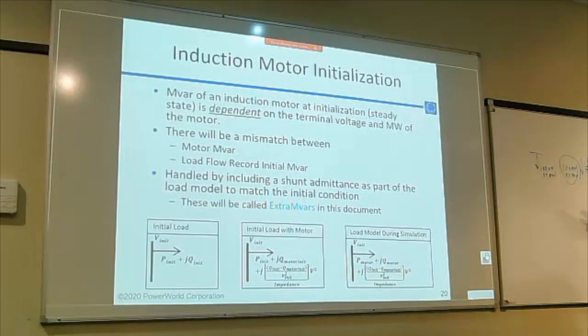All right, the issue is that I've seen support questions where somebody will have tripped like 90% of these motors. And so essentially this model's down to like 10 megawatts and 8 megavars. But when I look at the net showing up in the transmission system, you get this weird thing where the motor's supplying a whole bunch of VARs. And it's a reasonable thing to ask us, what the hell is going on? I thought I tripped it. It used to be consuming 80 VARs. Now it's providing 22 net VARs because that shunt is just hanging out.